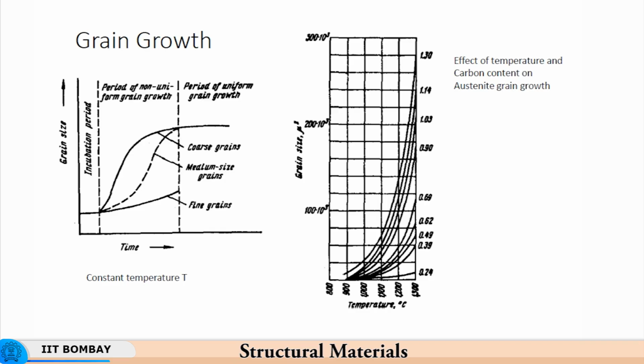You get ultra fine grain size, UFG. So, you have another level of fineness of grains which is much below this level of fine grains, it is ultra fine grains. So, the rate of coarsening of ultra fine grains will be extremely high. So, a very small amount of heat is good enough to start coarsening the grains, because there the surface energy is extremely high, and therefore, a small amount of heat is enough to get the grains to coarsen to minimize the surface energy.